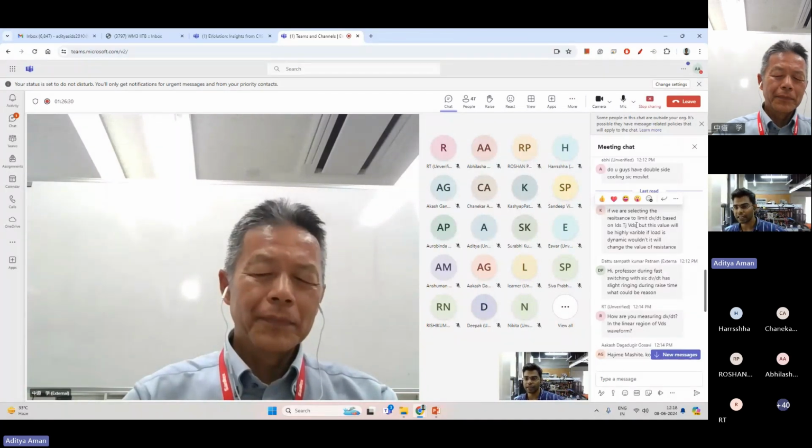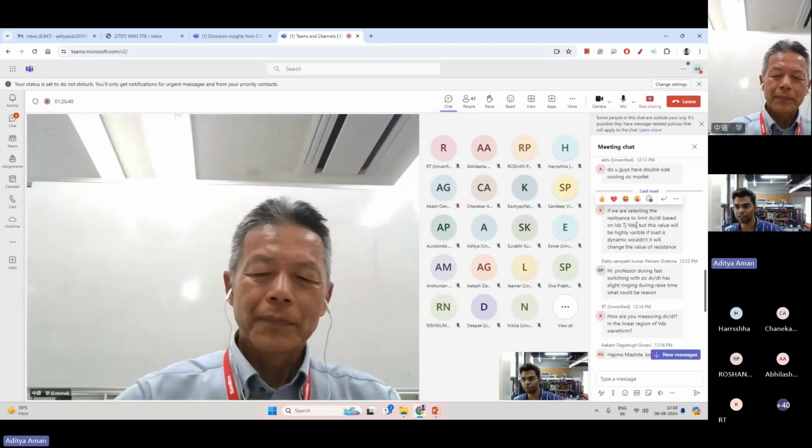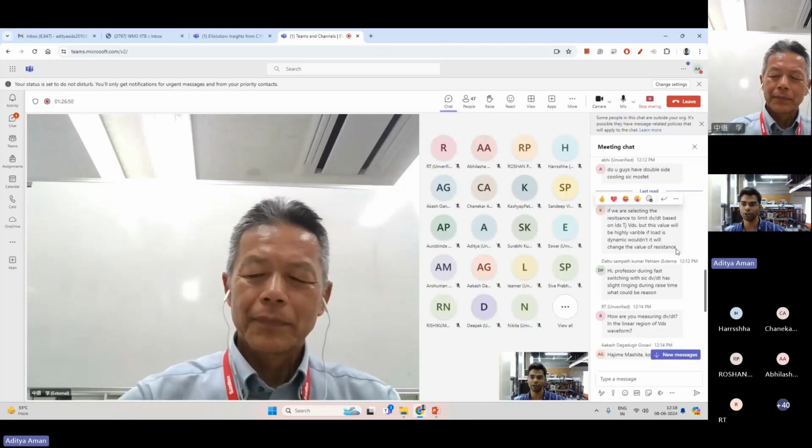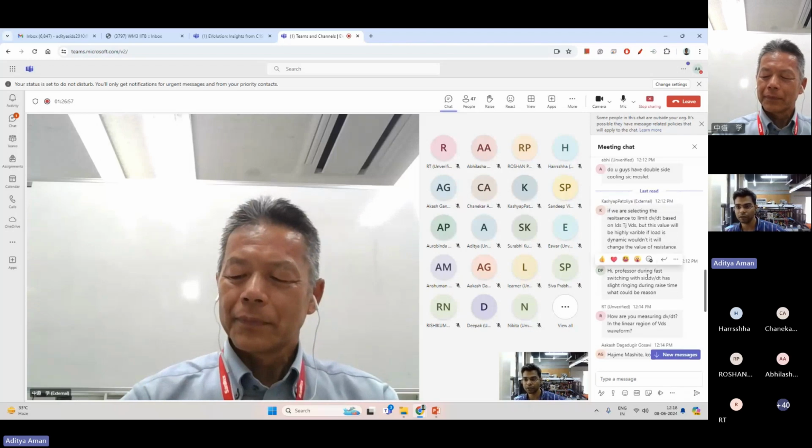As we had deduced, the worst operating case for turn on and turn off will be different. Like I had said that for turn on, it will be at minimum current, maximum TJ, and maximum VDS. So that is considering the dynamic condition. And yes, you are designing it for a dynamic scenario. I'll request you to go through the paper. It will clear this particular doubt of yours.